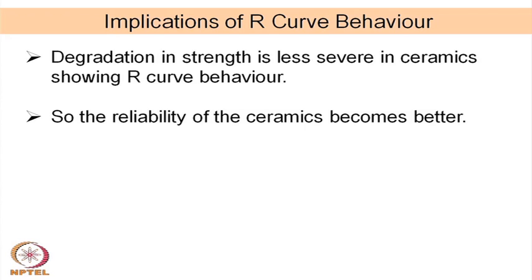That means, one of the major problems of ceramic materials is unreliability of the property, particularly the mechanical property, because of the fracture toughness, because of the brittle character. Once the crack propagates, it has a tendency to propagate at a very fast rate, almost a catastrophic failure takes place. So, it completely depends on what kind of cracks are already present there, or whether we can arrest those cracks by some means like a toughening mechanism and so on. So, there is always the reliability problem with ceramic materials, and that is one of the major weaknesses of all ceramic materials in general.